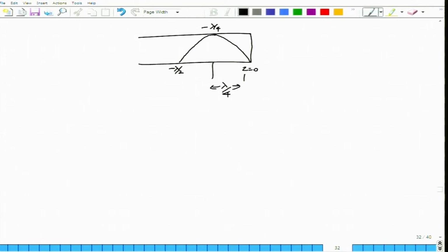Now, I consider a very special case of pure reactance termination. Suppose I consider the case where ZL is either an inductor or a capacitor. Suppose this is an inductor with plus jZ0. So, this is an inductor. You can clearly see that the magnitude of the reflection coefficient will be equal to 1, which indicates that SWR must be equal to infinity.